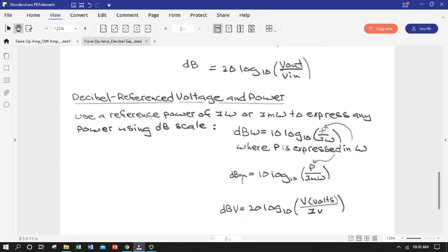A lot of times you may be working with low power output signaling electronics where we certainly hope we're not generating 100 watts of power. We'd melt our circuit. So we might be looking at things on what's called the dBm scale, and this is a little m, and it stands for milli, as in the 1/1000th scale in the metric system. So in this case, the only difference is whatever power we're looking at is referenced to 1 milliwatt. So this is going to be a much bigger number because we're dividing by a very small number. But we have to remember that there's the reference. So the same power expressed in dBm is going to have a bigger number than that power expressed in dBW.